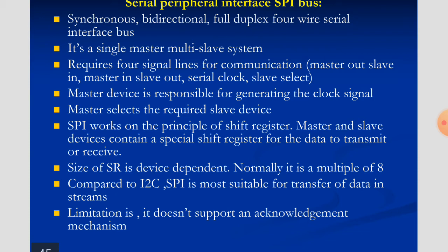The master device is responsible for generating the clock signals, same as I2C. Again, the master device controls all the operations. The master has to select which slave device is required for communication. All these decisions are taken by the master device.